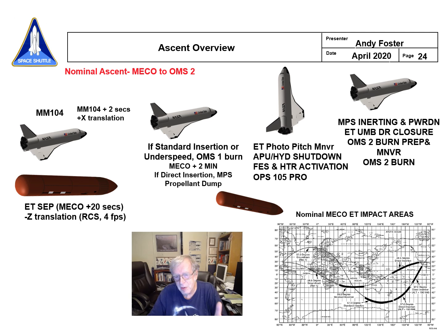And then we take the software to OPS 105. Remember, as I told you earlier, 105 is a software mode that we need because it's got the stuff in it that's going to let us do an OMS 2 burn. And so we pro to 105.